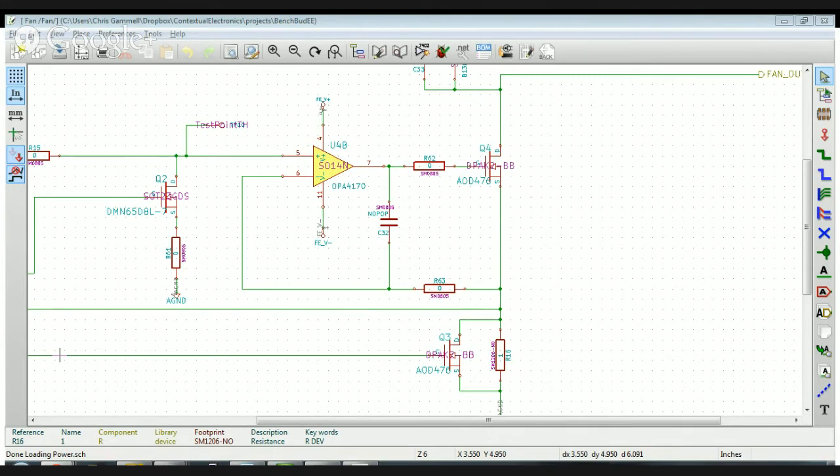Would that be right? It's like a quarter, less than a quarter amp, right? So then we get 256 steps within that. So I think the big thing is if we really want to get smaller, we need to buy the 12-bit parts. That would definitely be the biggest thing. We could have the best of both worlds if we wanted higher current and smaller steps if we went to a 12-bit part. But I guess that's where we'd have to pay as well, right? If we want to pay for nicer parts and then also probably more accurate initial resistors for the sense resistor there. Be interesting.